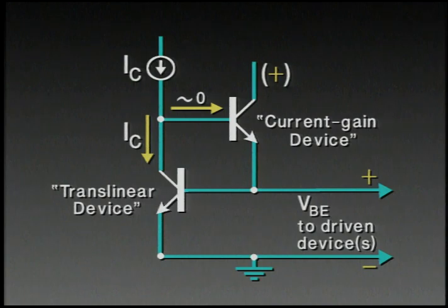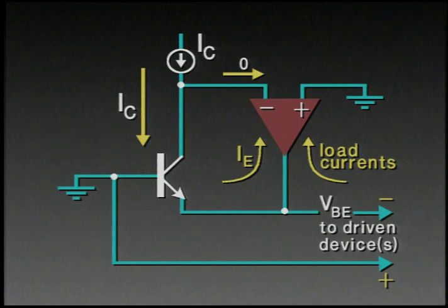One practical problem with this circuit that needs to be taken into account is that there is a beta loop with two poles, and if not taken care of, this can be an oscillatory circuit. I don't plan at all to talk about dynamic effects today. It's of course a big subject, and it would require detailed discussion of each particular circuit on a case-by-case basis. So we will assume that in a practical design we'll take care of some of these dynamic issues with the appropriate additional circuitry.